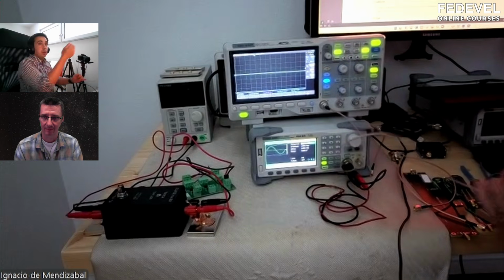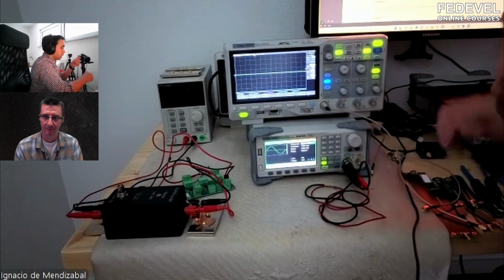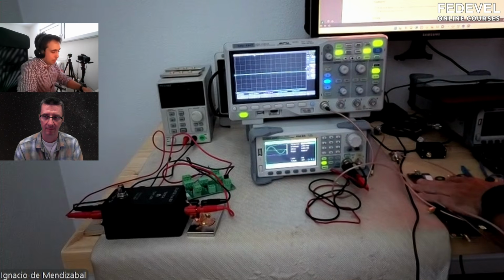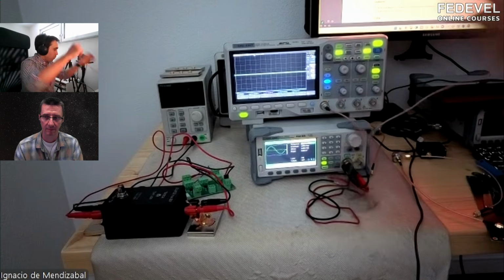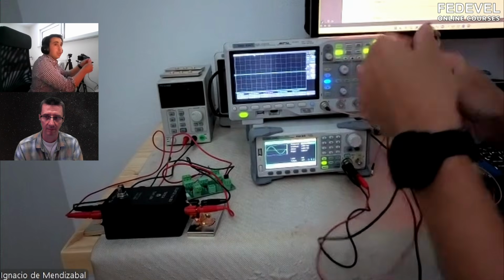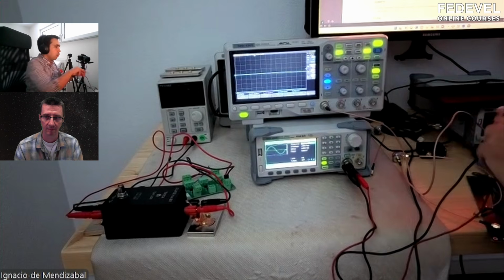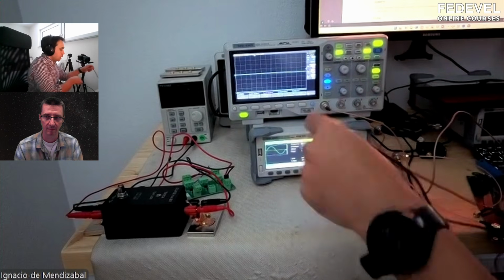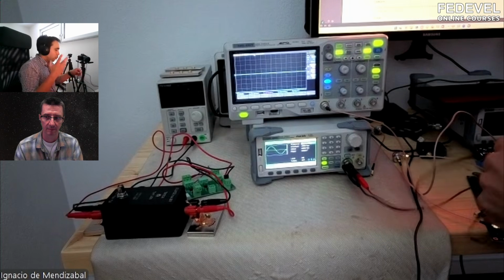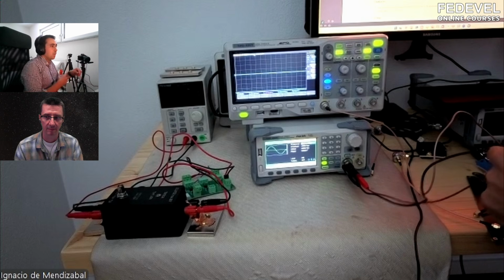Okay. So here what we have is an oscilloscope, and for now it's completely open. There's nothing here. At the same time, we have a bunch of probes, but what we want to measure is really simple. We have the signal generator, with one cable connected to 50 ohm, and then one cable coming back to the return. What we want to do is compare what a near field probe can measure versus what we are injecting.